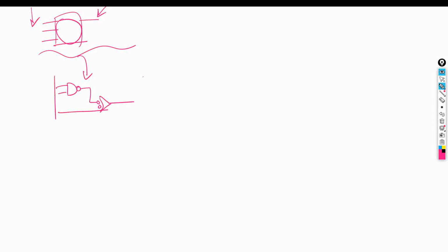How do you get a set of logic, that, hey, this has 3 inputs, 1 output, and you are basically constraining whatever inputs you get based on the expected output? This is the logic you have written. This logic is converted into gates. Actually, these are all cells. NAND cells, NOR cells, these are all the standard cells. In the synthesis stage, you'll generate standard cells.